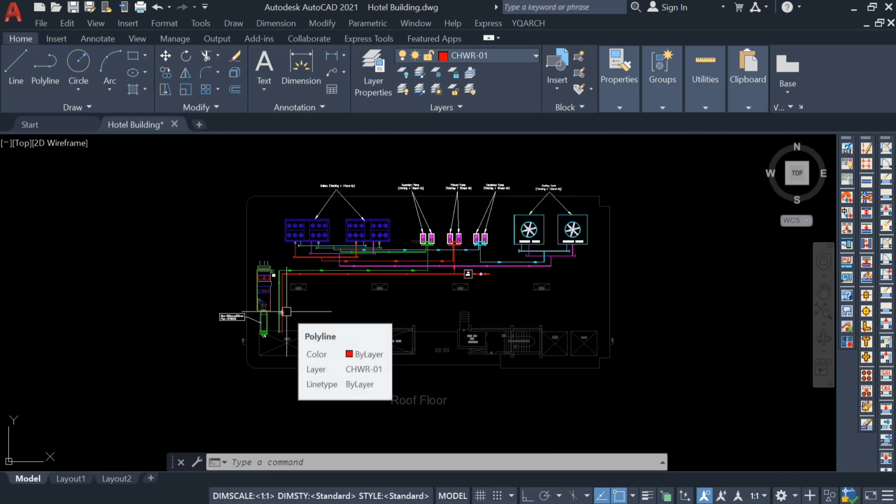When you are doing the sizing for a closed loop piping system, you have to remember, in a closed loop chill water system the flow rate of water required to provide 1 ton of refrigeration can vary depending on factors such as the temperature difference between the supply and return water, the type of chiller and the design of the system.